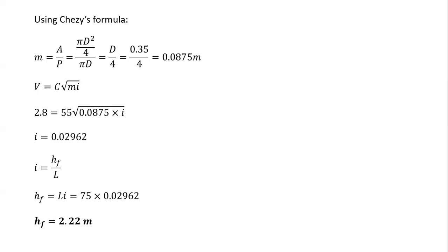Now, you can already see that Chezy's formula is usually useful when you're just trying to make an estimate, because even the value is smaller despite the other one giving us a bigger number, showing that if you want to get something more and more accurate, you may go for the other one. Even when you want to design such pipe flow, with this there could be some assumptions that you may get rid of. But here, this is our final answer using Chezy's formula.